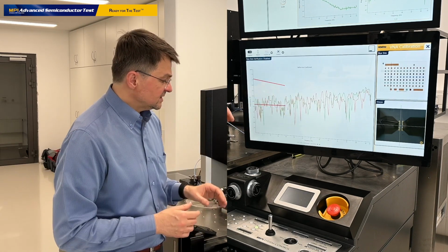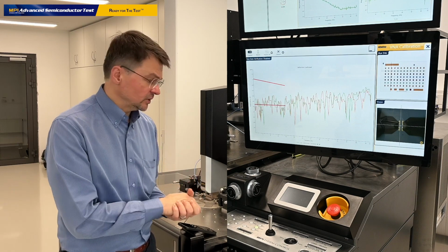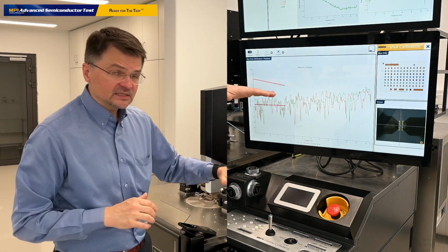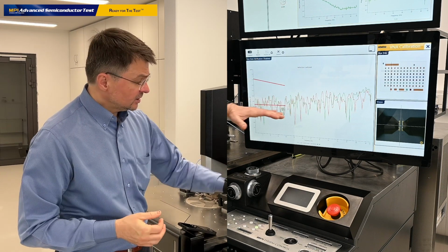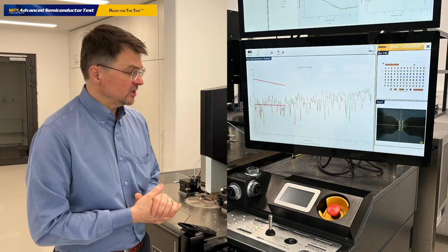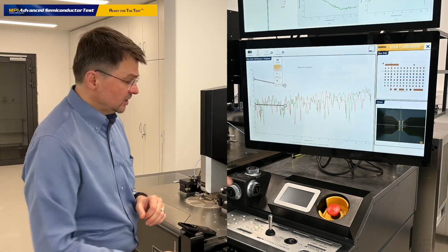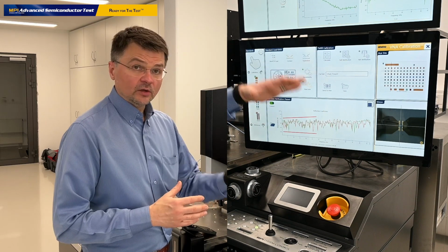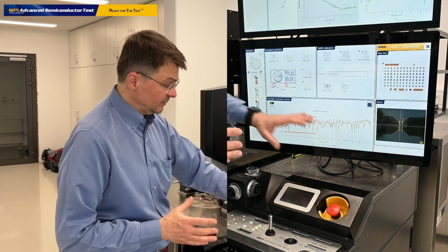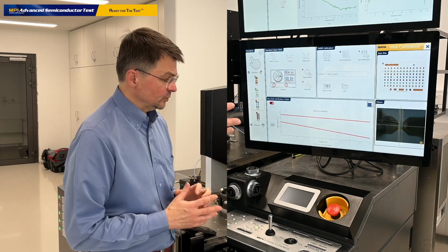And for the raw data, when we have good impedance matching conditions on the load standard, our return loss on the load should be better than 20 dB. Here, we have initial settings which were configured for some other measurement conditions. So let us reconfigure them. So we measured the data on the load standard and we adjusted the boundaries for the load standard. Everything is as it should be. Let us move to the next standard, which is the open standard.